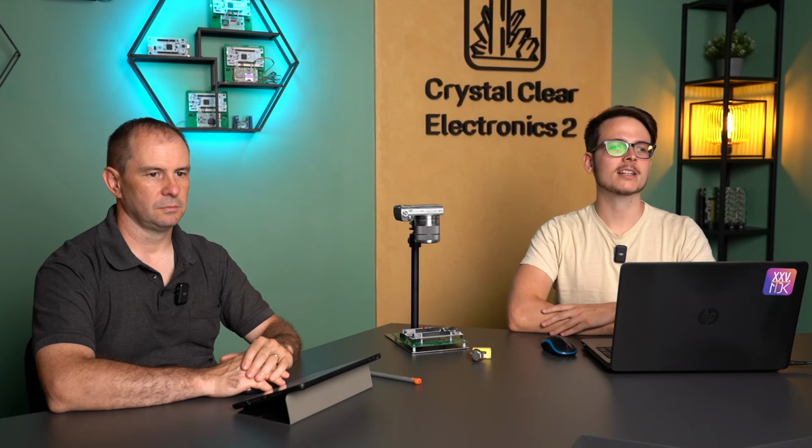The SysTick is a 24-bit resolution down-counting module that is set by embedded operating systems during the initialization phase. Its timing can be changed in the operating system configuration parameters, and at its expiration the operating system scheduler runs and decides which tasks to run. This timer will be important in chapters 21 and 22 of the curriculum, since these chapters are about operating systems running on microcontrollers.